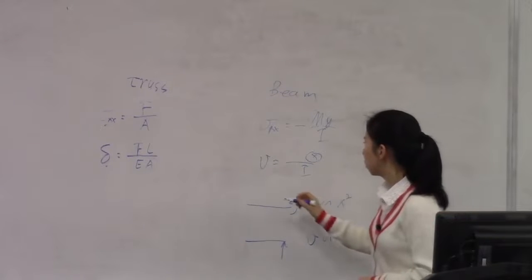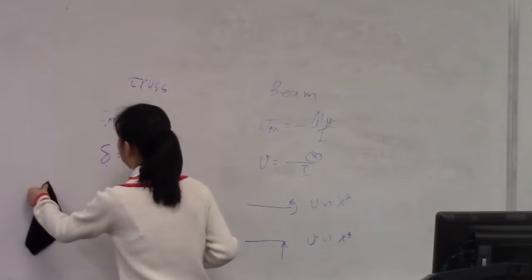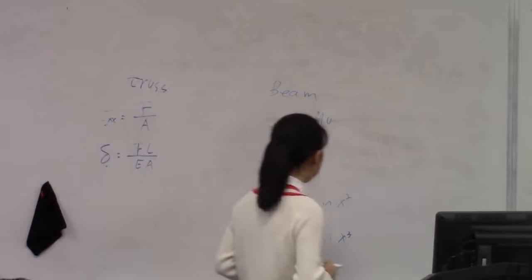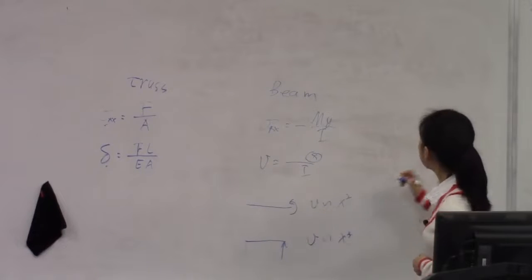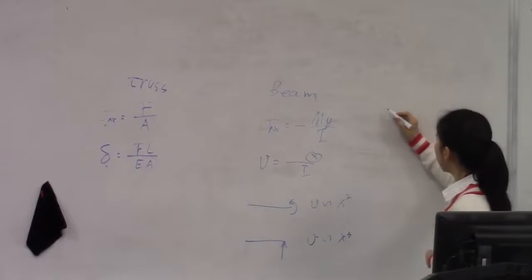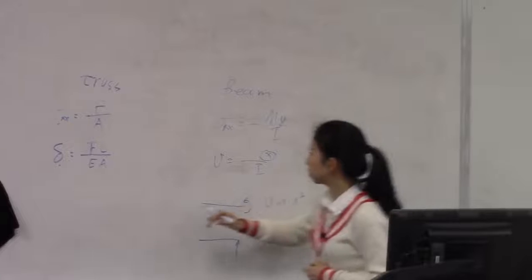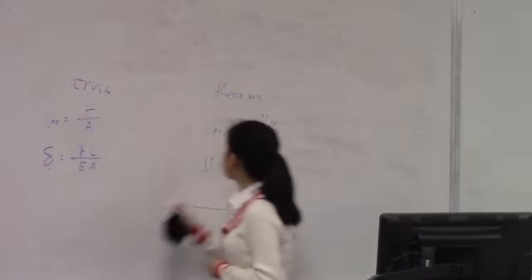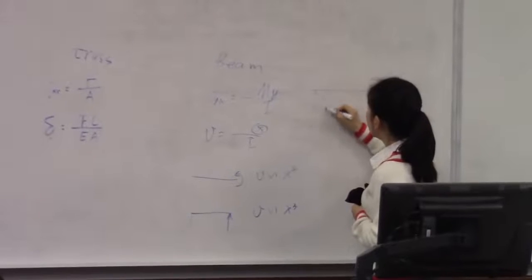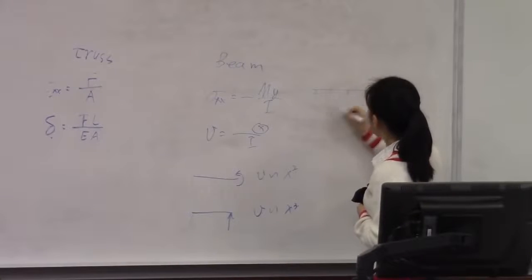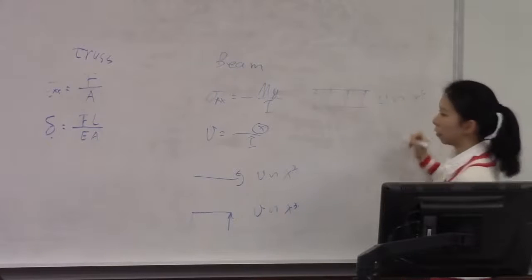Okay. Because normally in FEA we use U as a displacement in x direction and V as a displacement in y direction. So this V is a deflection, the displacement in y direction. And if the loading condition is a constant distributed force, this deflection should be 4th order, right?